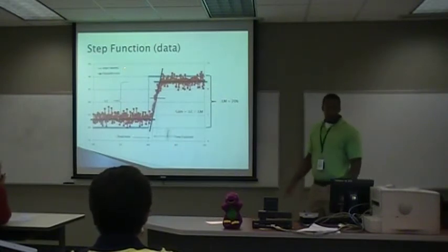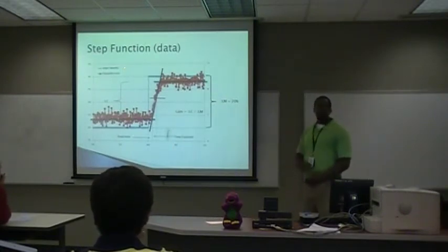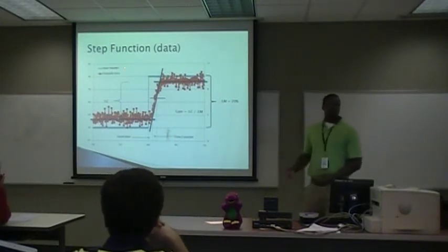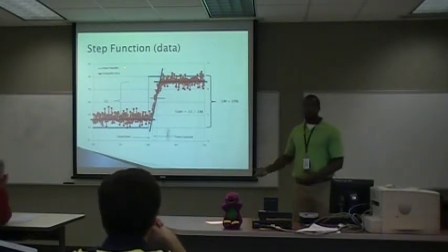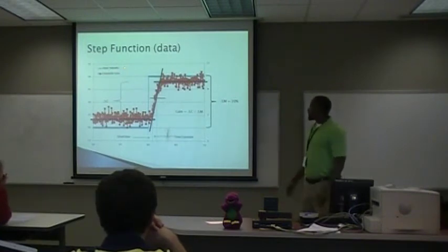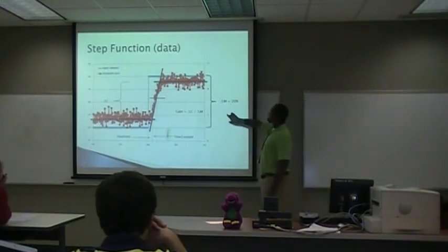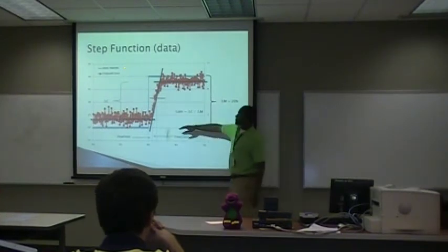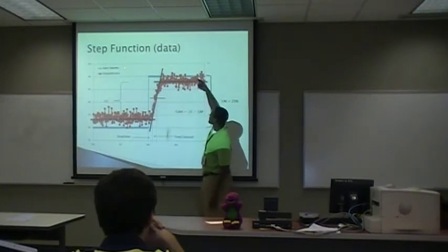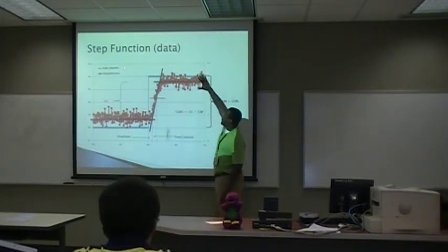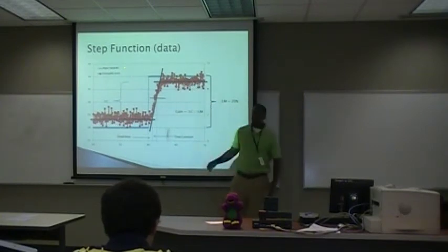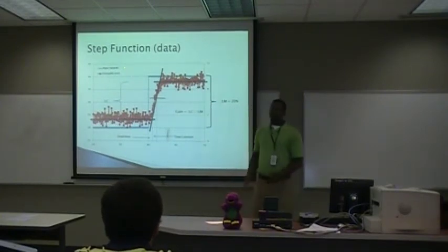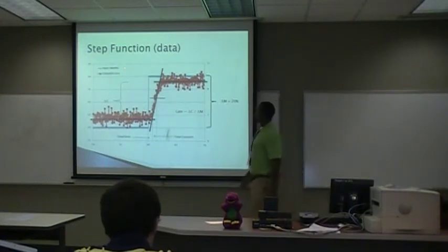What we ended up doing was we ran it at a particular input and ran it long enough for it to reach a steady state. Then after so long, we told it to increase its input by a particular percentage, which in this case was 20, and then we plotted the output and did our analysis on it. As you can see, delta M being the change in the input being 20%, delta C being the change from the general average of here to here, which, like I said, the fluctuation in values kind of indicate an oscillatory response, and I'll get into that a little bit later.